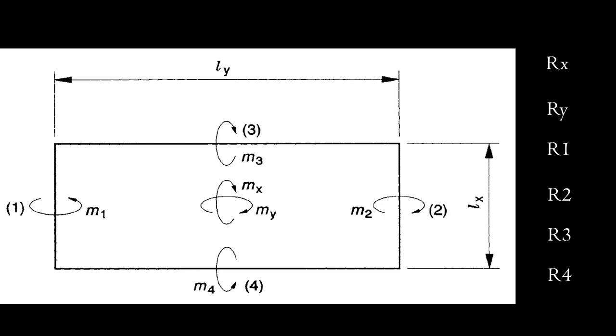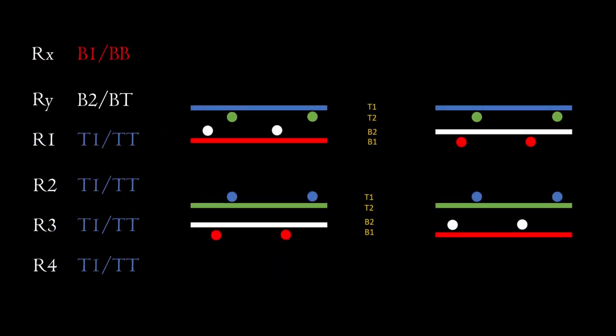In slab detailing, we have 4 layers of arranging reinforcement. So you can arrange reinforcement either using this first method, as you can see, where you have the bottom reinforcement, then you have the one above it, then you have the top reinforcement, then you also have the one below the top reinforcement. In a two-way slab, all these reinforcement provided are categorized as the main reinforcement. They are main reinforcement because we designed for them. They are important so as to resist moment.